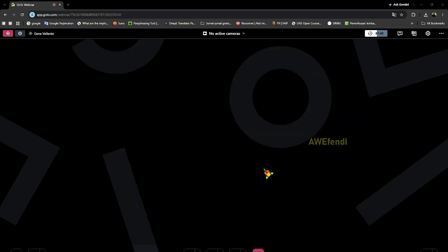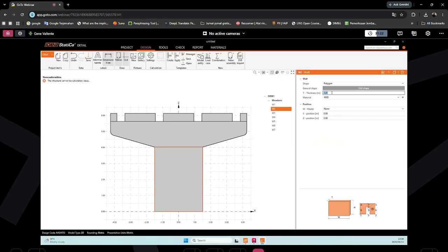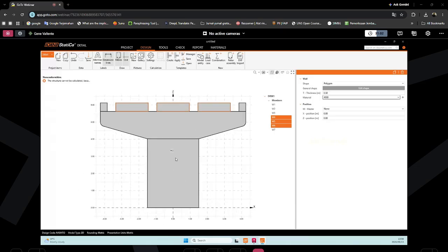Of course, we need to have correct geometry of this. We need to adjust our thickness here. So the thickness of our parapet is actually 1.8. And the thickness of our pier is actually 1.25, which is a circular one. And at the end, this will follow the same thing. I can just press and hold the control button, 1.8. And at the same time, I can also press it right here and change. This time, this is 0.5.